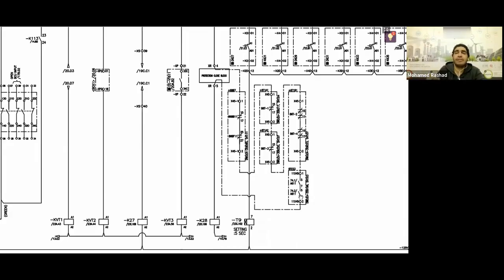Consequently, in the event of a fault, or if I want to open the breaker, I find myself unable to open it. As long as I can't open the breaker and a fault occurs, the breaker failure function will immediately activate, and I will find the station or the bus bar completely out. So it is not logical, as long as I know in advance that the breaker's tripping circuit has an issue.